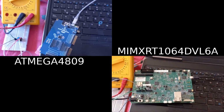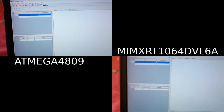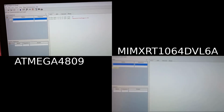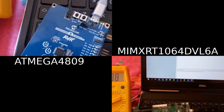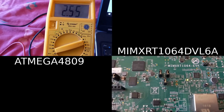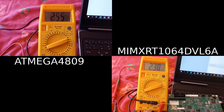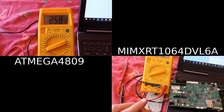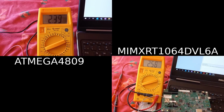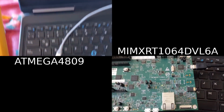And now we can see the code actually running on our board. So we have it connected through UART to the computer, and we can check the messages on Docklight. This tells us that the UART module is working. We can read the voltage as we can see it on the multimeter, and that message is being correctly carried through the UART to the computer. So all of these peripherals are working correctly.